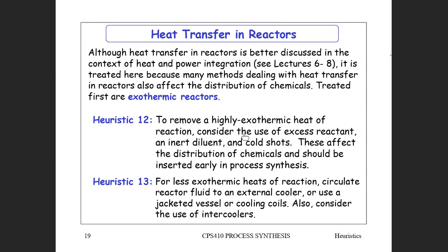You've probably done combustion reactions in first or second year, where we've got a fuel and we've got oxygen, and the adiabatic temperature rise is in the order of 2000 degrees C. But because of running these things with excess air, excess oxygen, you've got nitrogen, which is an inert that is absorbing some of that temperature rise, and you will operate a furnace which is burning fuel at about 1300 degrees C, the flame temperature. So that is a highly exothermic reactor, of course.